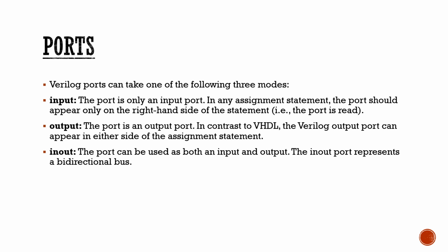Lastly, ports. Ports connect a module to the outside world. There are three types of ports: input ports, output ports, and in-out ports. The input ports receive data from outside. Example, input A comma B. Inputs can only be read. Output ports send data outside the module. For example, output sum. Outputs hold the result produced by the circuit.